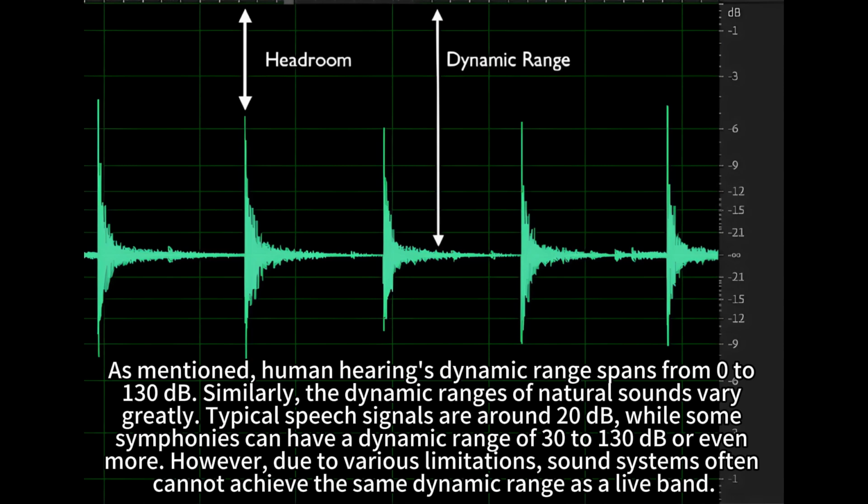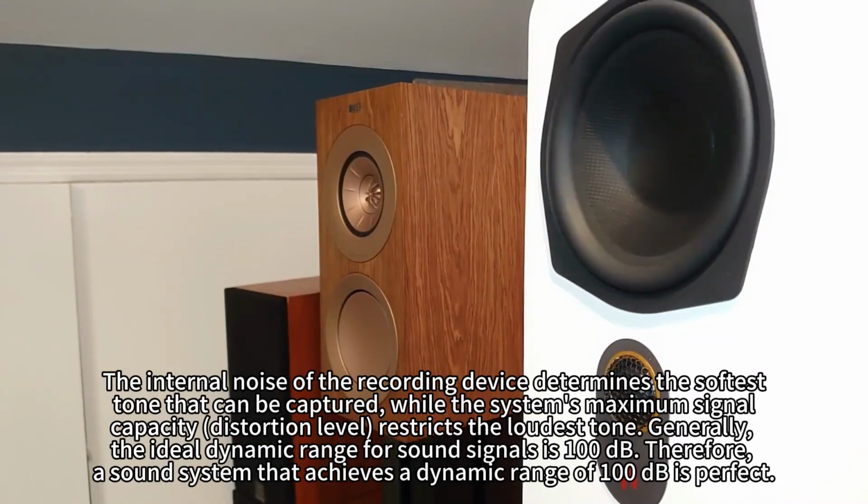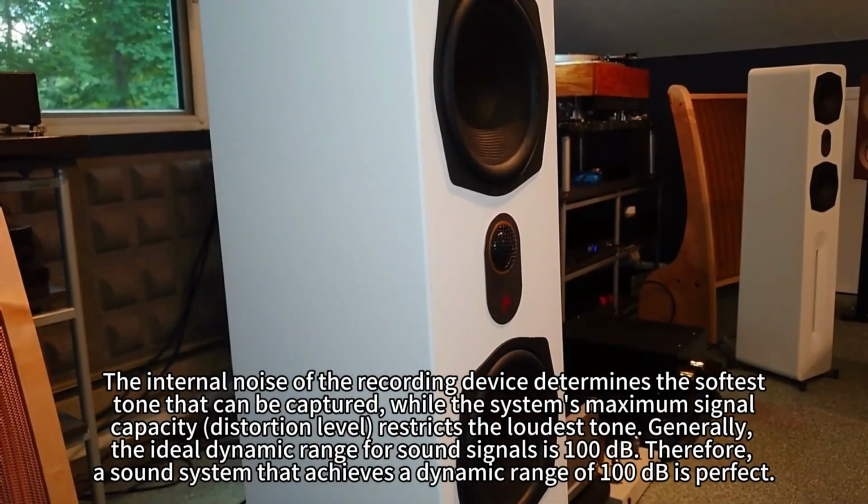Similarly, the dynamic ranges of natural sounds vary greatly. Typical speech signals are around 20 decibels, while some symphonies can have a dynamic range of 30 to 130 decibels or even more. However, due to various limitations, sound systems often cannot achieve the same dynamic range as a live band. The internal noise of the recording device determines the softest tone that can be captured, while the system's maximum signal capacity and distortion level restrict the loudest tone. Generally, the ideal dynamic range for sound signals is 100 decibels. Therefore, a sound system that achieves a dynamic range of 100 decibels is perfect.